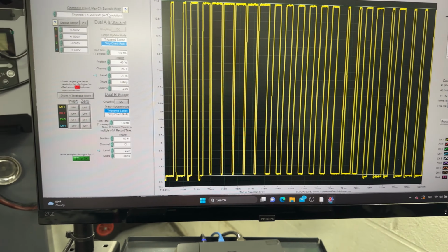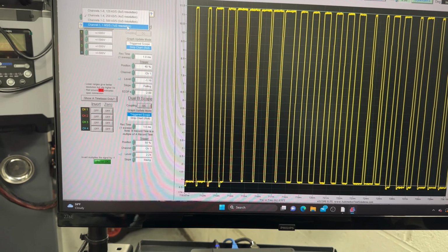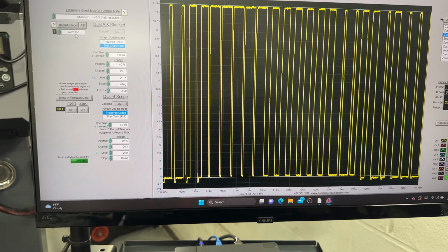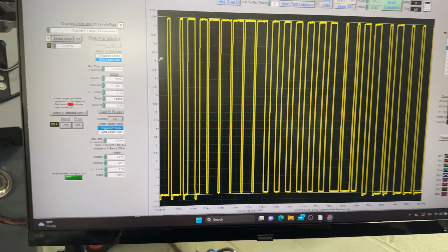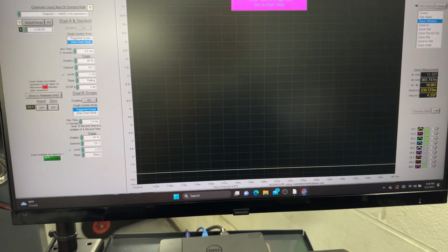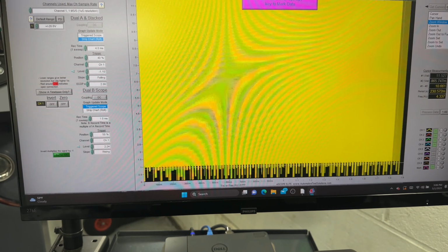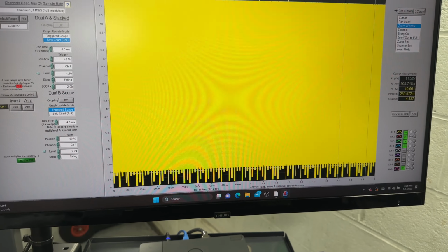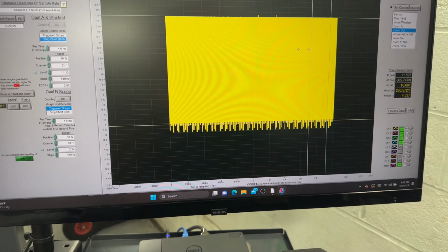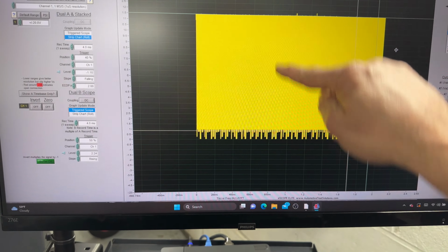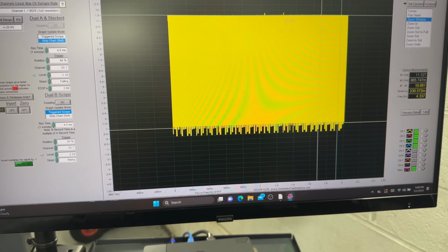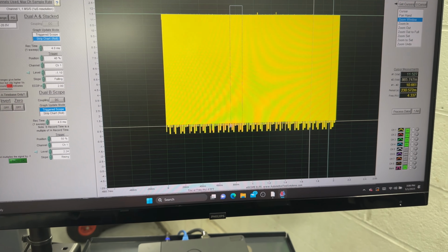But if I go and reduce this and make it go even to one channel, to 20 volts, I'm in a strip chart, not triggering the scope because I don't really need that. And now I start the recording. Now this is a lot better. The way I like to do it is to zoom out, because now I can grab a window higher than the signal to analyze the information a lot better.